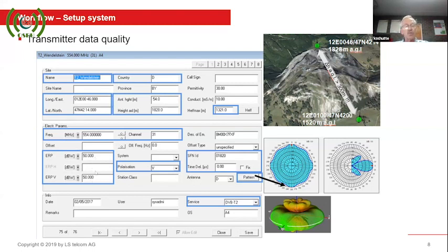So that will tell you how much power is being transmitted in that plane. Then if you've got a single frequency network, you will have a unique single frequency ID. And that unique single frequency ID will then appear at all the stations that use that same frequency, which is synchronized in the network. Then there's also a parameter regarding time delay that you can introduce to simulate networks and to reduce interference.